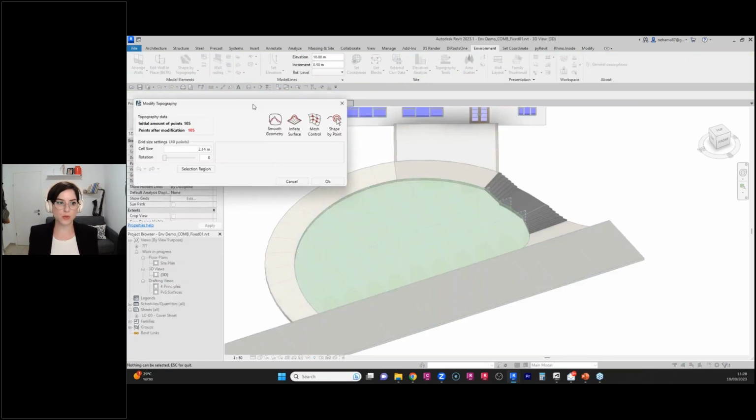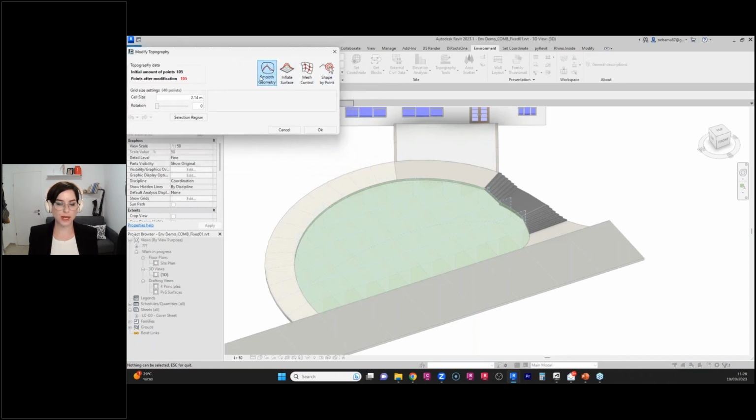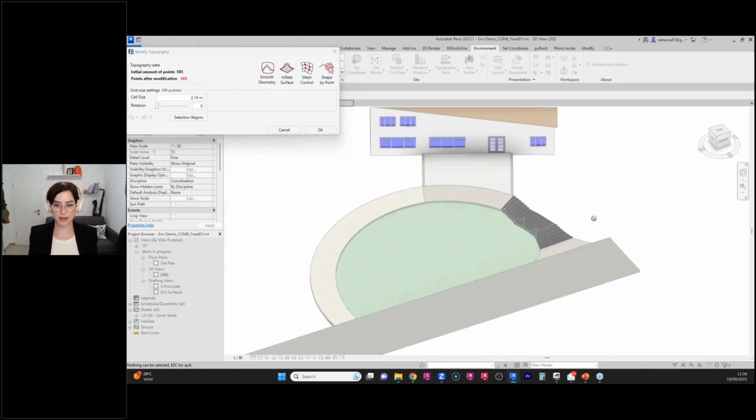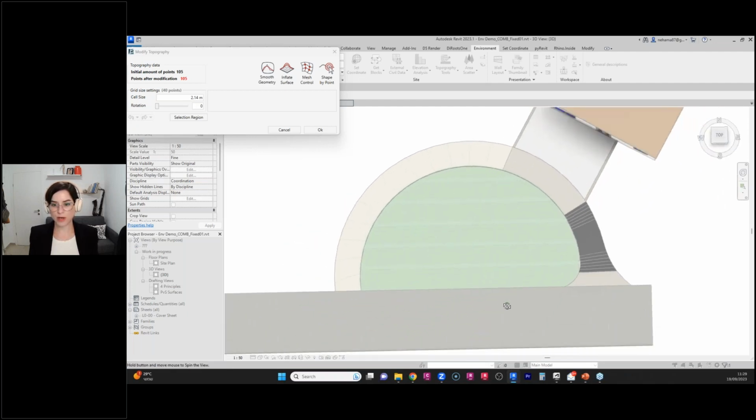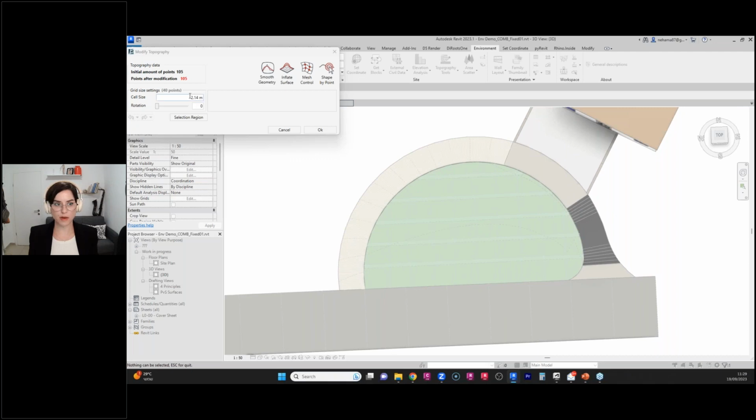And you can see that over here as well, we have a tool set that can do many, many things. I'll show you two examples. So first of all, I have a grid on my topography. The meaning of the grid is that instead of placing points like before in a very accurate and thoughtful way, what I'm going to do now is Environment will spread a net of points over my surface, thus allowing me to get a very, very smooth result.